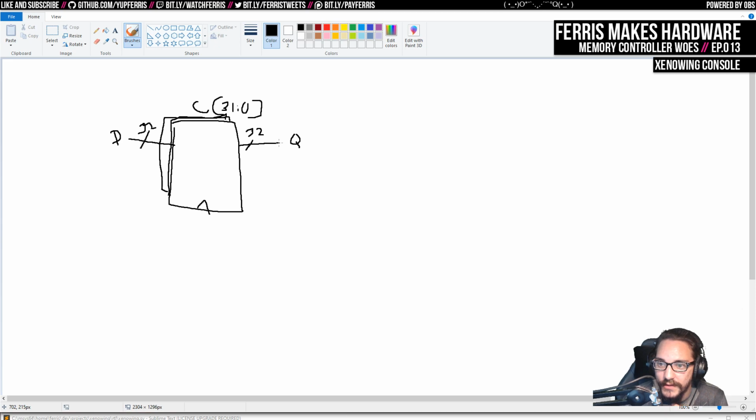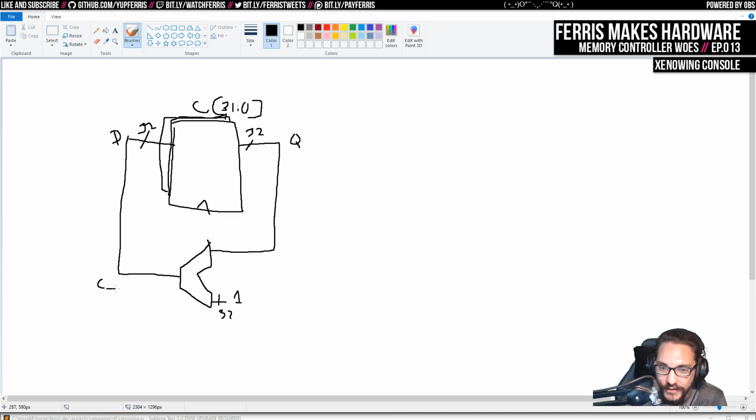And what I do here is I have a little thing here, this is 32 bits. And then I have this value here, and I call this counter next, which refers to this part of the design. So essentially I have this counter that's increasing by 1 every cycle. And this is how you would design that: you have this register, and then this adder here. The interesting part is that I also have some logic about when this is going to reset.